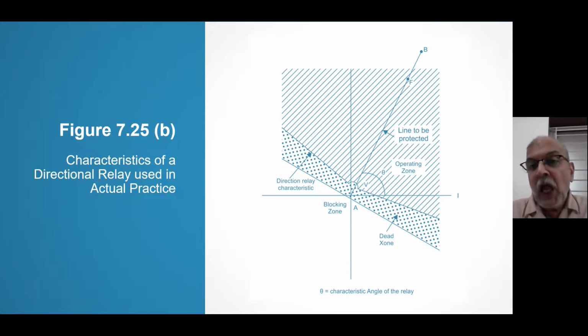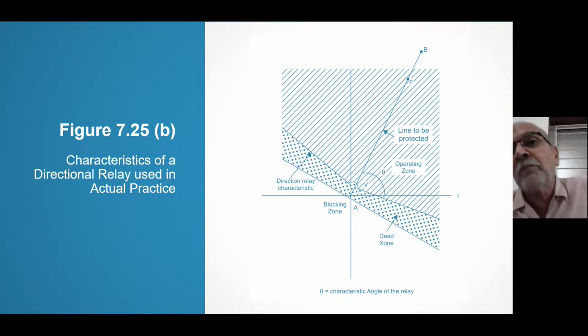Then to IR I am feeding VYB. Now even if an RY fault occurs just after the breaker, then VRY is zero. Forget about 1 volt or 2 volt, it is just zero. Even then I am not feeding VRY. To R I am feeding VYB and to Y I am feeding VBR. VRY I am not feeding at all. So for a double line fault there is no dead zone.